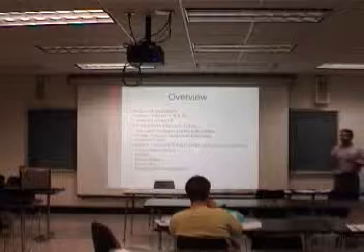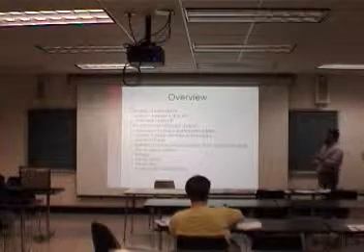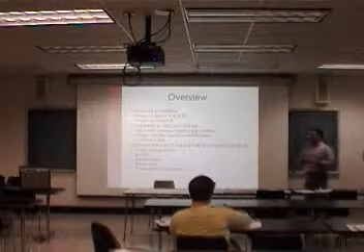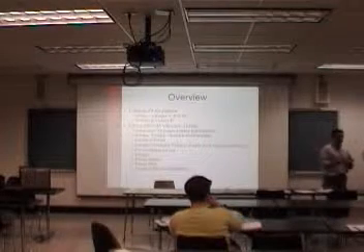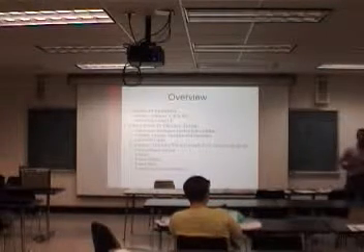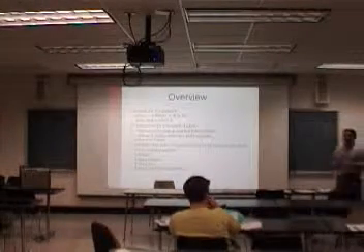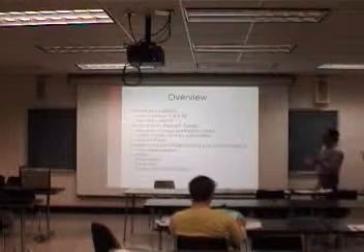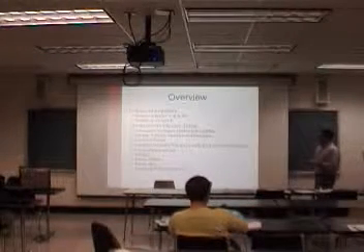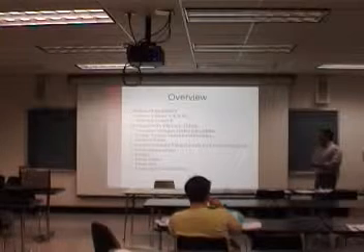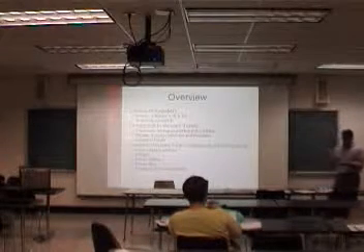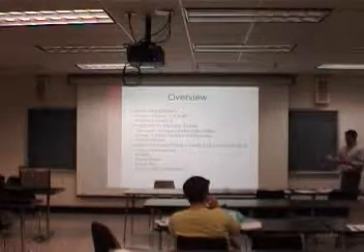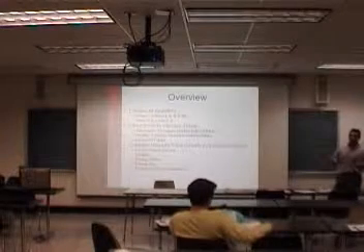But the newer ones were slight tweaks that add a little bit more, so you get like the 7027A, which is like a 6L6, but you can run a little higher voltage and get a little more power out. So if you design those in, it's not really that much of a design change, and you can put the 7027 in, and then you can sell it in higher numbers. You add to the market.